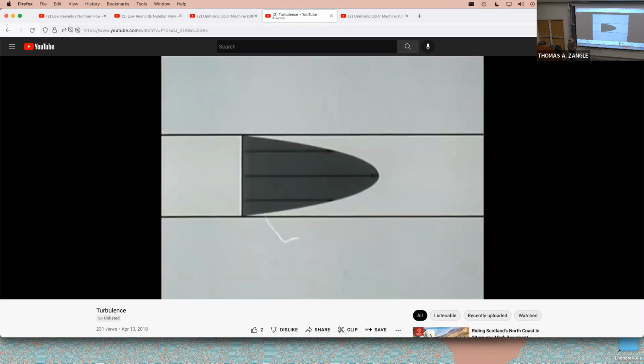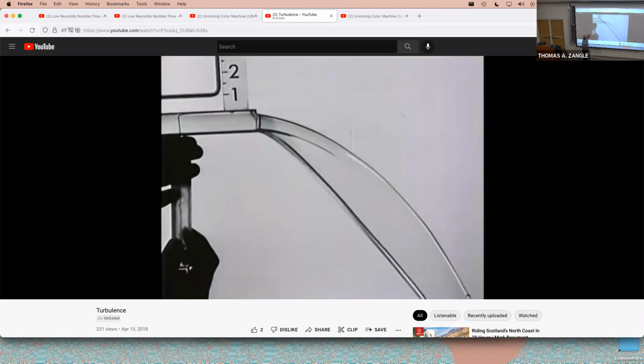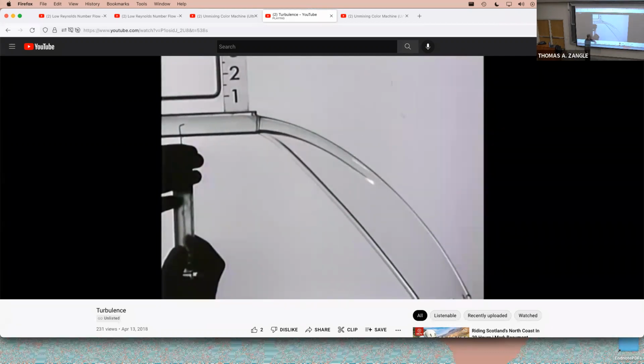In laminar pipe flow, the velocity profile is parabolic. Near the wall, there is a considerable quantity of relatively slowly moving fluid. Dye injected near the wall departs with slowly moving fluid. When it leaves the pipe, it falls with a steep trajectory. Notice that the slowly moving fluid near the top of the pipe also falls steeply. The rapidly moving fluid from the middle of the tube falls with a flat trajectory.